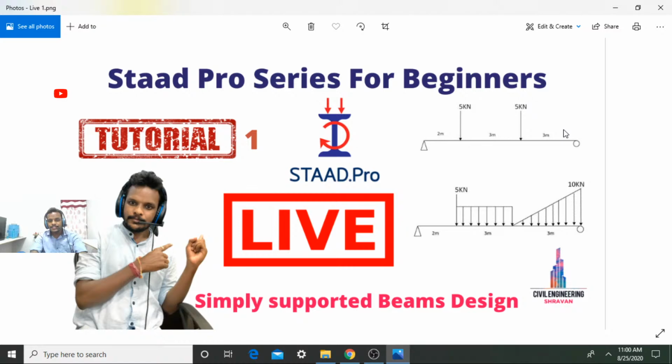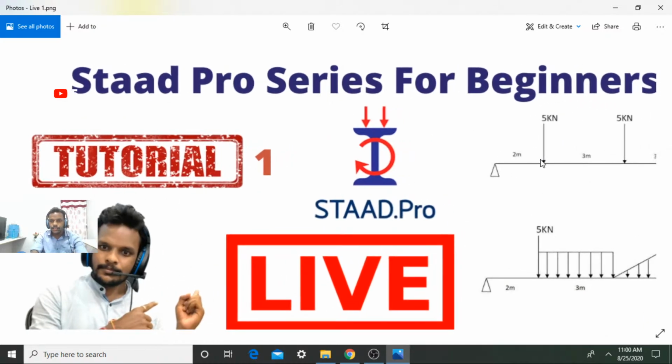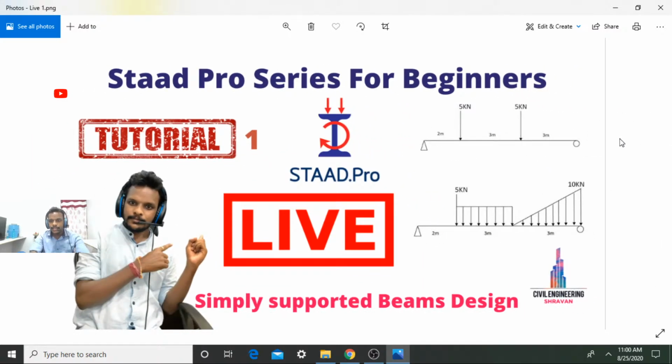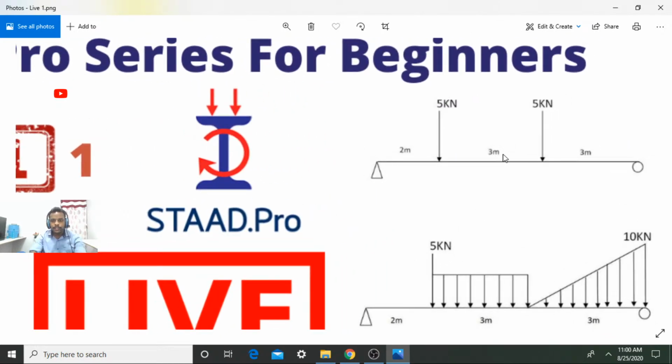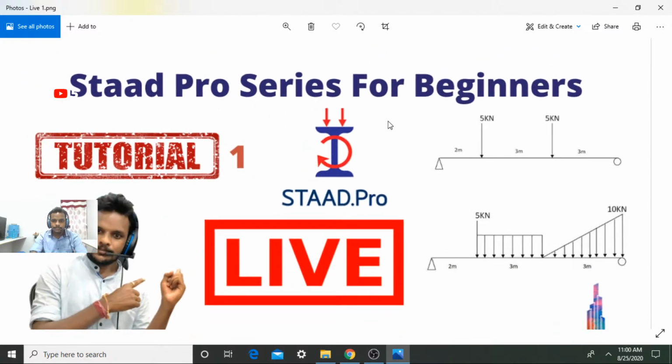The beam consists of a 5 kilonewton point load, which is acting at a distance of 2 meter from the left support and 3 meter from the right support. The left hand support is a hinge support and the right hand support is a roller support. So we will design this simply supported beam by using STAAD Pro software with the help of this 5 kilonewton point load.